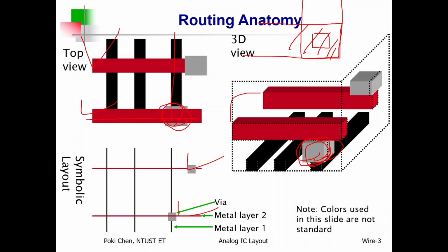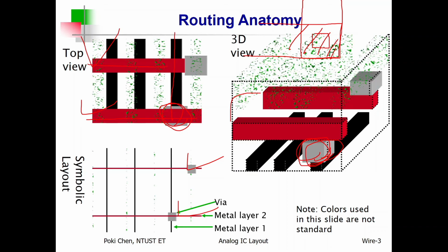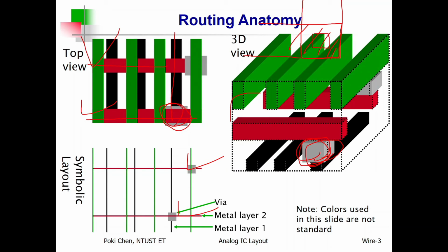So, if you would like to connect this one to another metal 3, then you still need the help of another via between metal 3 and metal 2, and so on. So hopefully you get a correct understanding or feeling at least about such kind of 3-dimensional wires. Not only for wires, for everything. Everything on chip actually is 3-dimensional in such kind of overall structure.